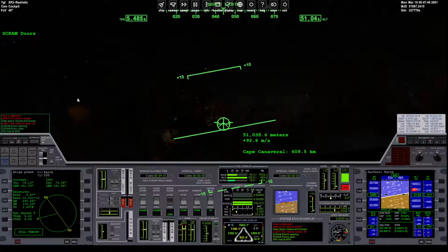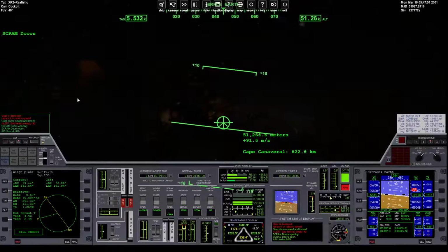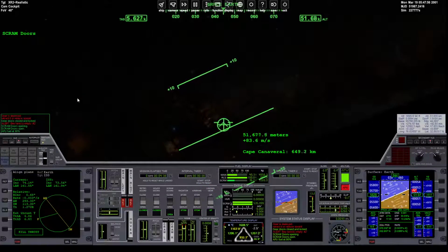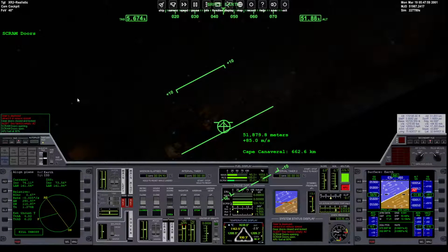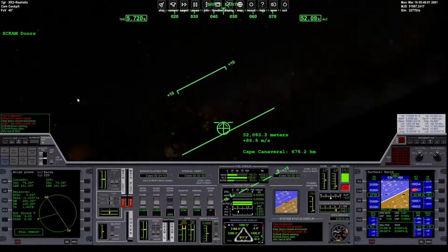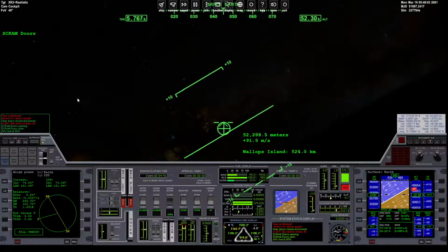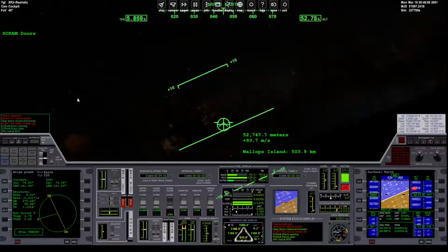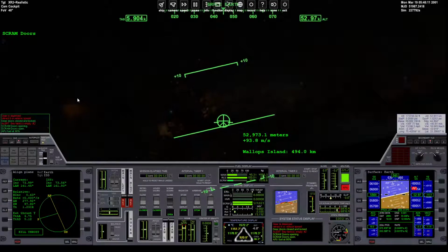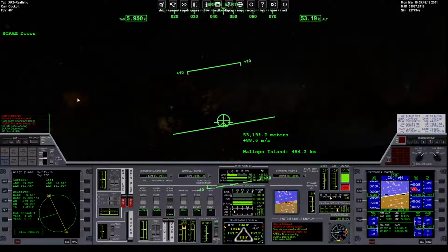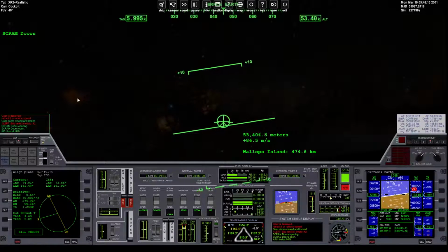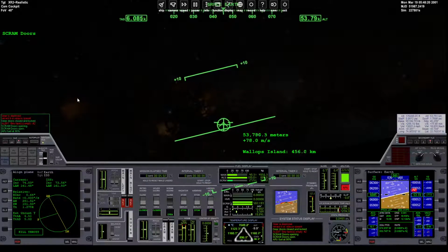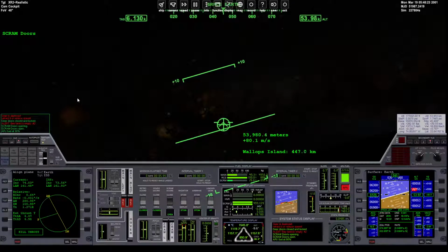See, with the scram ascent with our XR2, it's a lot lighter than a stock XR2. Actually, it's a lot lighter than stock because I put the oxygen levels down to more realistic levels. Well, not realistic, but it carries a lot less, so it's overall a lot lighter. Plus, I removed the crew habitation module that default spawns in it. And the basic difference here is that we're going to be encountering our scram temperature limit well before we actually run out of scram fuel.